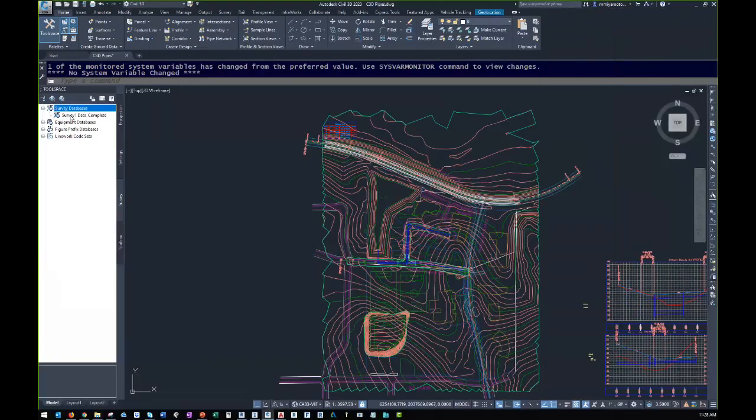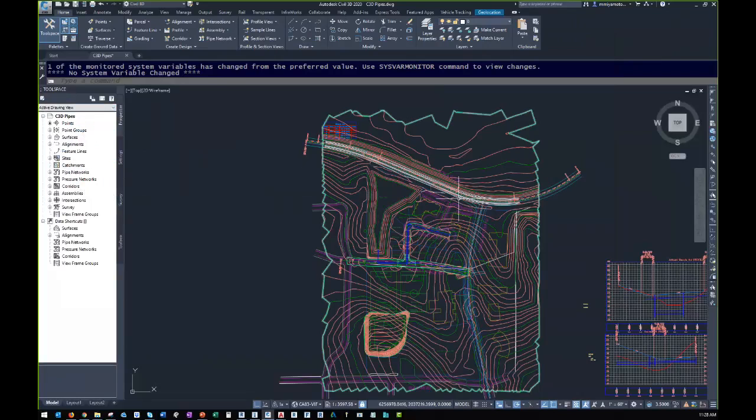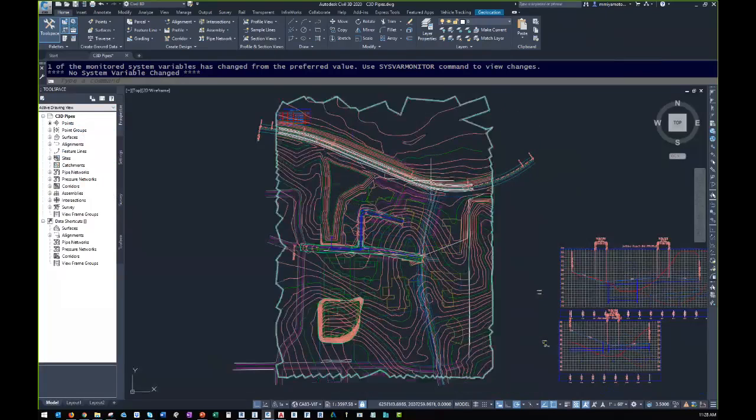And then that also pops up in the drawing file. We've got all of our same figures, all of our same survey points with the import events still listed there, but now in that new format that is compatible with 2020. And then, of course, just a reminder, this is no longer compatible with 2019 or 2018 since it is a different format of that database. So this is specific to 2020. Any changes we make there are going to be accessible via that survey tab in this version only.